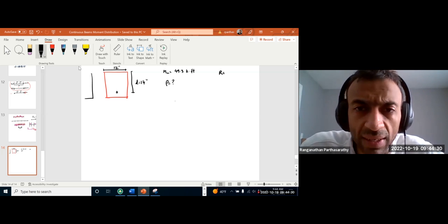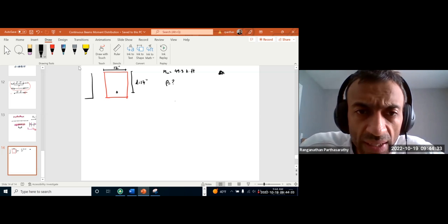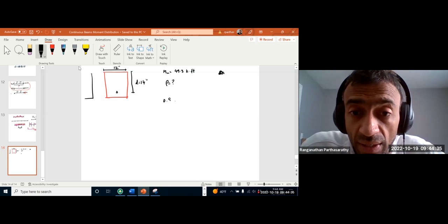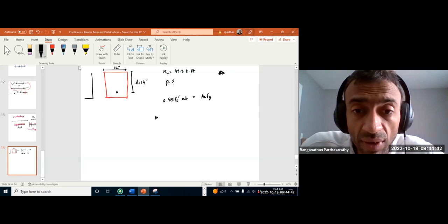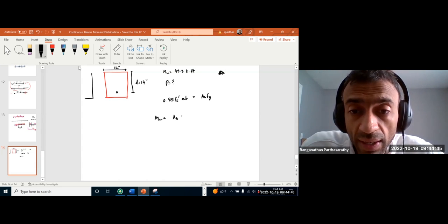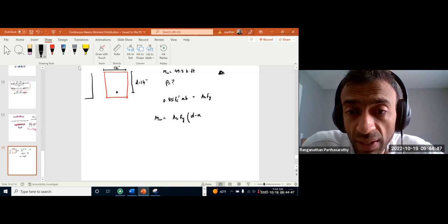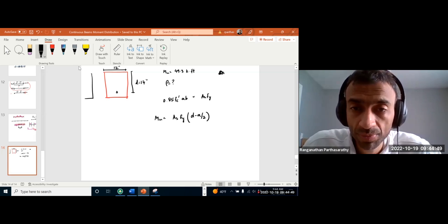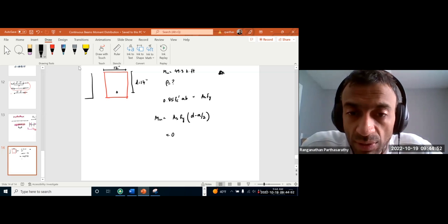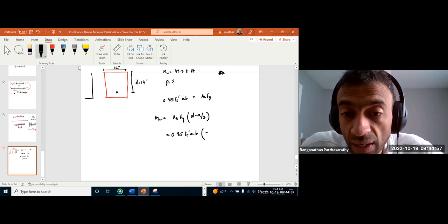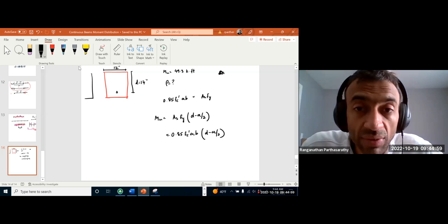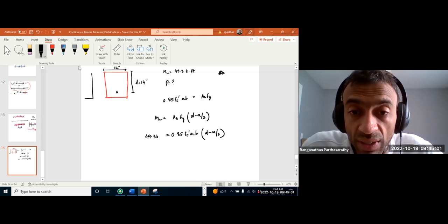First, let's do it from scratch: 0.85 fc' a times b is As fy. Then our Mu is As fy times d minus a by 2. So this is 0.85 fc' a times b times d minus a by 2, giving us 49.3 kip.